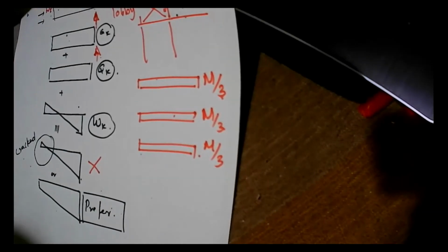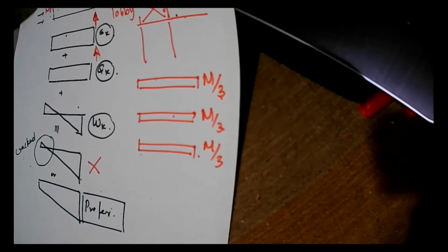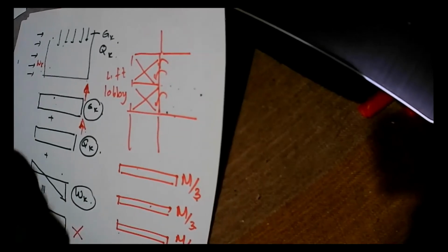So there are 2 options available. One option is, have a greater number of shear walls. The other option is ensure that you are transferring adequate load onto the shear wall. And if you have a situation like this, where you have another opening on the other side also, that may not be very attractive, because this particular shear wall will not have enough vertical loads to suppress the stresses caused by the bending moment.